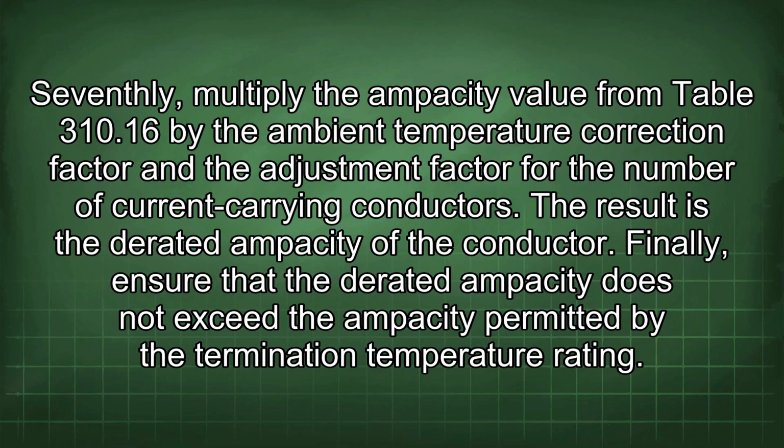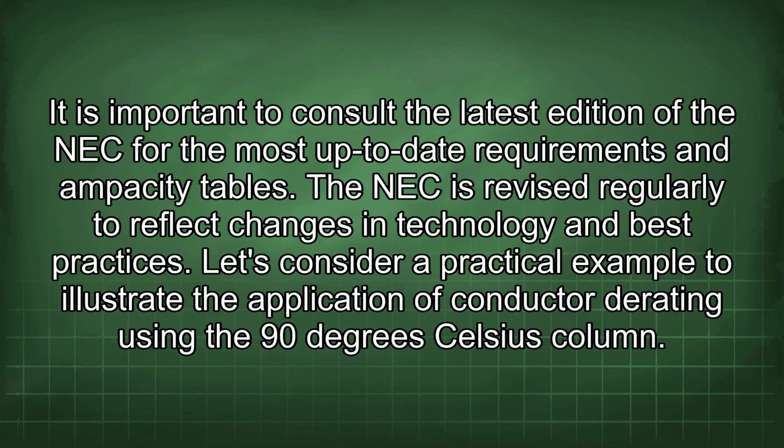Finally, ensure that the derated ampacity does not exceed the ampacity permitted by the termination temperature rating. It is important to consult the latest edition of the NEC for the most up-to-date requirements and ampacity tables. The NEC is revised regularly to reflect changes in technology and best practices.